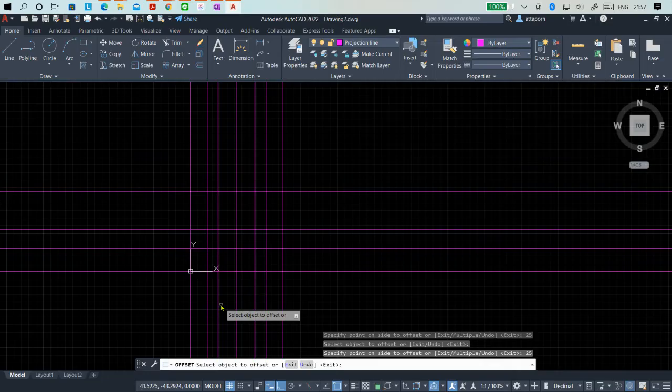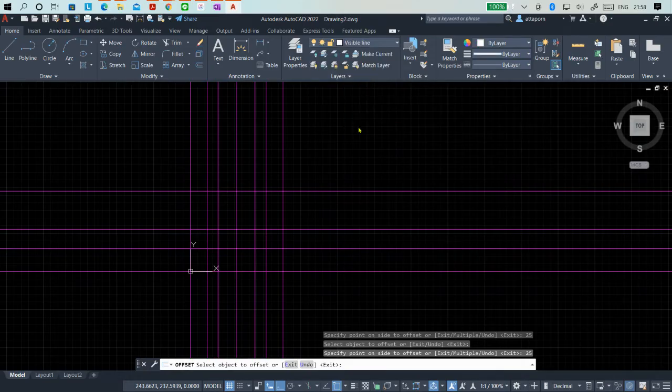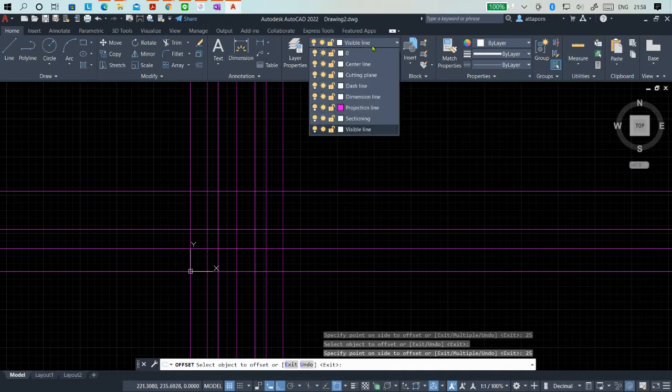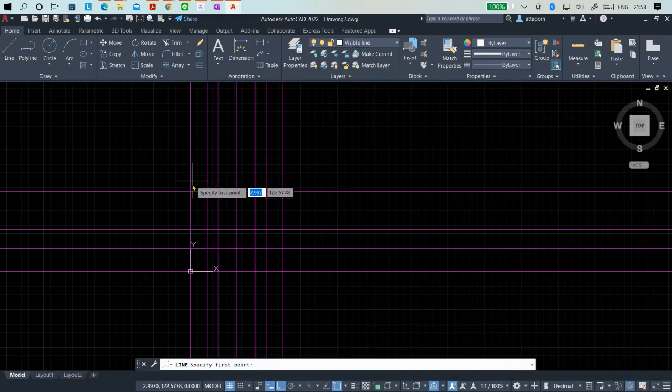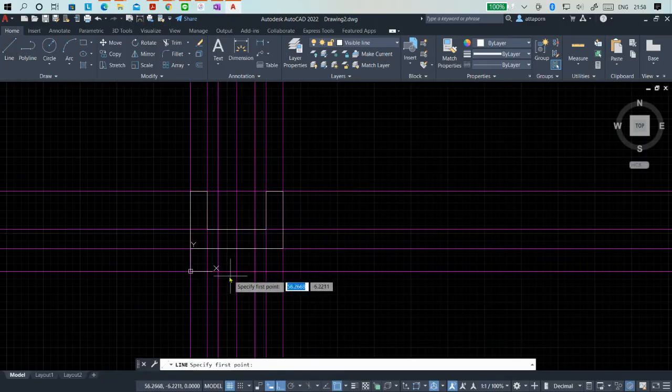Next, before you go on to the side view, or the front view, or the top view, excuse me, you can put a visible line to show some draft first. So choose visible line and line, and you draw maybe here by this, along to show the front view. Enter to leave the command.